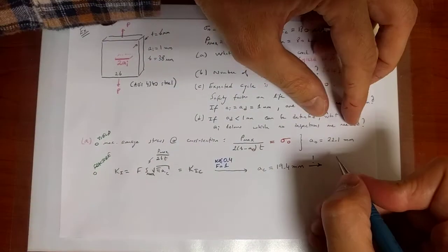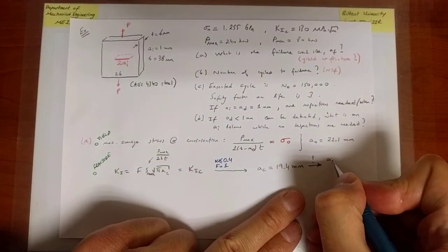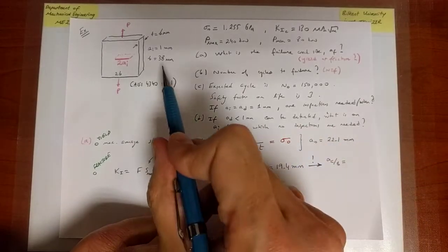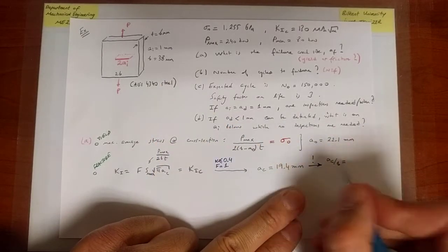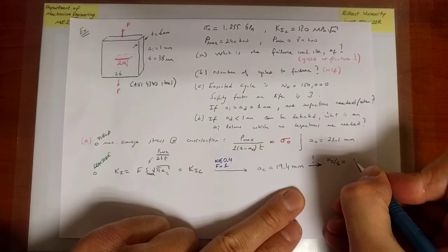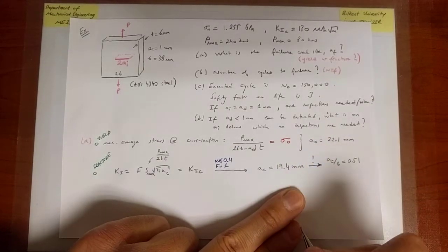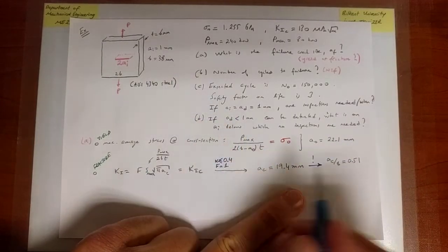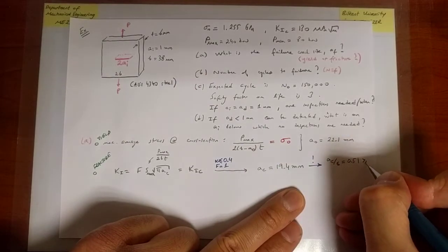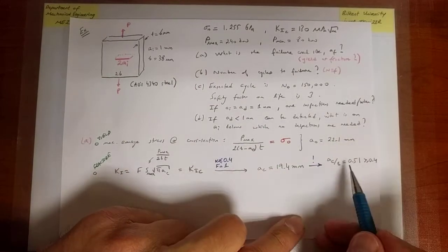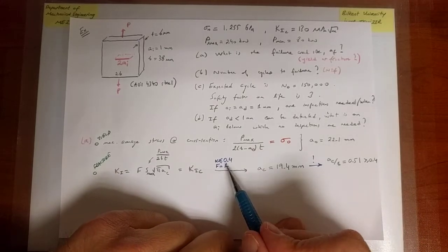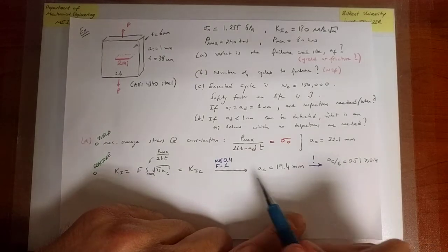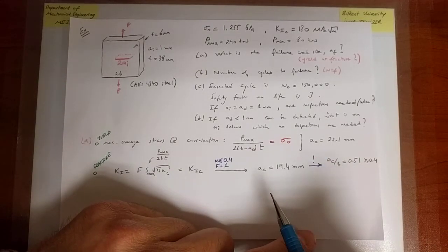Now, it turns out in this particular case that AC over B is equal to 19.4 divided by 38. You can already see that it's larger than 0.5, so 0.5 would be if this were 19 versus 38. It's 0.51, which is larger than 0.4, and therefore I'm not done. My assumption is violated, so I have gone beyond the 10% limit on K1, and I don't know how far I've gone, because F is increasing very rapidly.